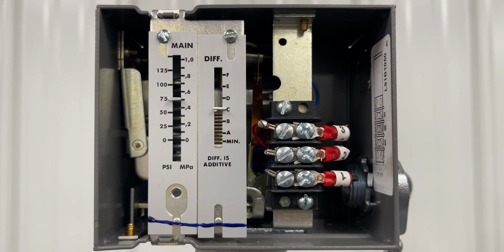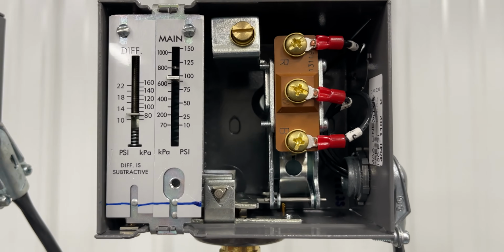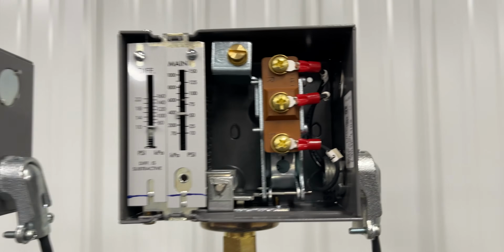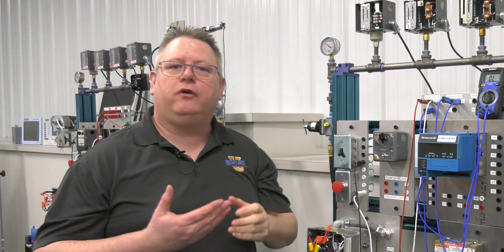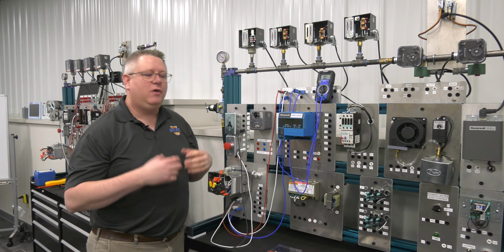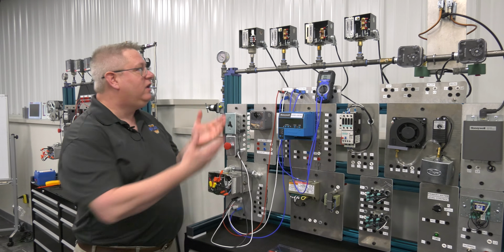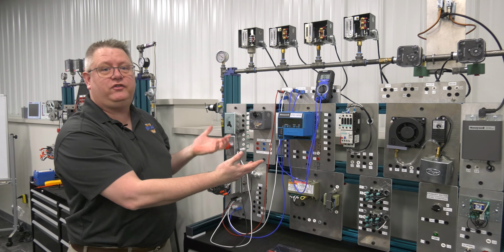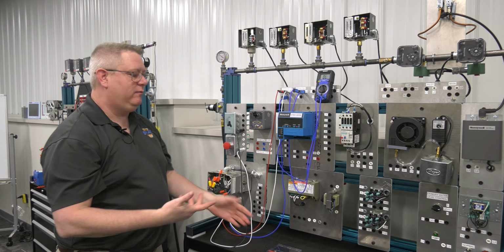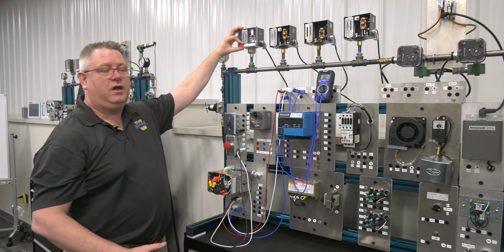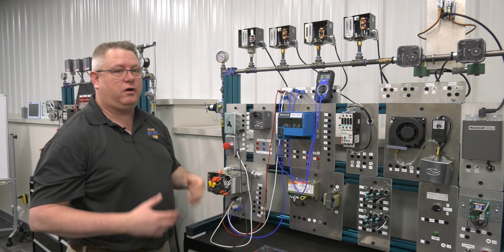A firing rate control, an operating pressure control, a high limit control, and in some cases a low fire hold control. Now, those are 4 different controls and they have different jobs. We're going to look at them individually. A couple tips on these controls. They look quite similar, so I'm going to differentiate them for you and give you some suggestions. First, they should have their covers on them, but we're going to take those off for our purposes.